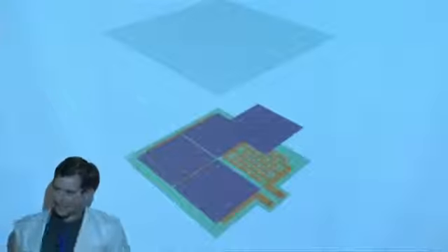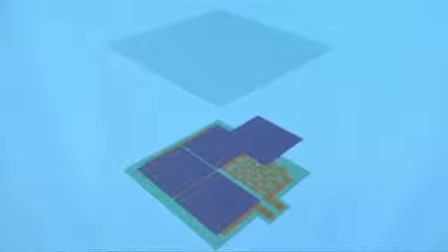The grid pattern on that cell is a radial spider web pattern that emanates from that central point and collects current from nearby. Essentially, an area about that big is collected by that little point right there. And then there's a hole drilled through the solar cell where the metal is wrapping through to the back. That's where it's making contact with the backside right there. And then there are other regions of the solar cell that are making contact with the bulk, the base, if you will. So you have both your N and your P-type contacts on the backside of your solar cell, and that's what's shown in this drawing.